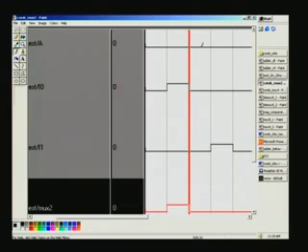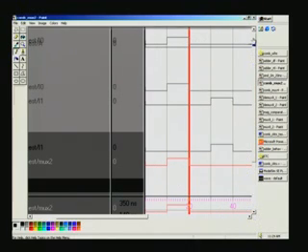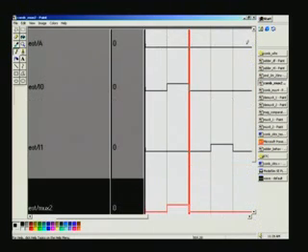I1 will be selected only if A is 1. So whatever is the input waveform here, this must appear at the output. That's precisely what we have here, right at the bottom. You can see here, right? And beyond this, it is continuing to be 0 as far as A is concerned. Therefore, this pulse being low here, beyond this, it continues to be low here.